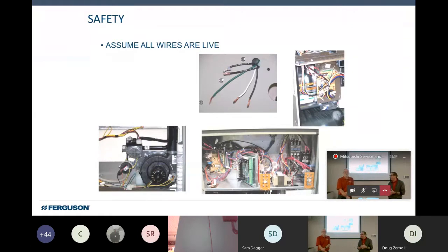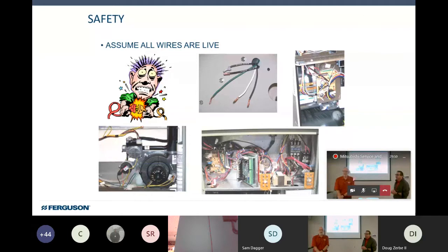But please remember that you are working also with DC voltage when it comes to the ductless line. I know we have pictures of what we're normally used to seeing as far as AC voltage, but we are dealing with DC on these units. We don't want that happening to you. We use very high DC voltage, and DC will bite you harder than AC will. We've got over 300 volts DC in some places off these boards, so we must be very, very careful.